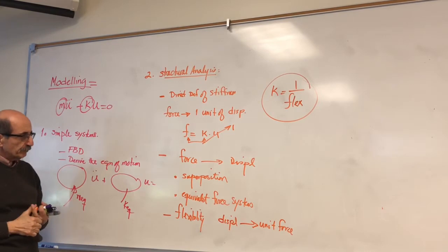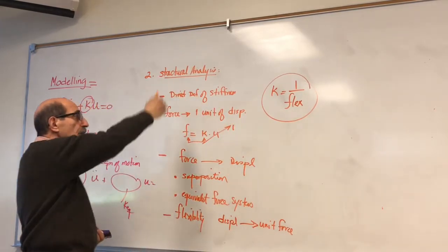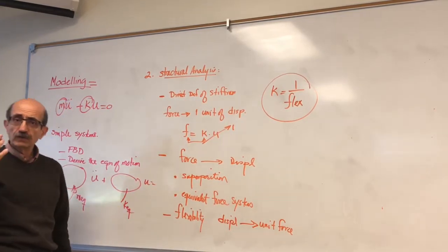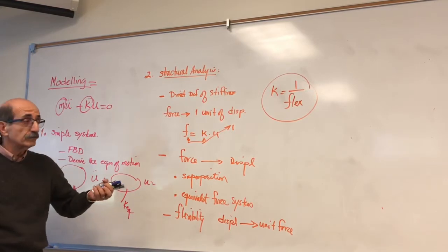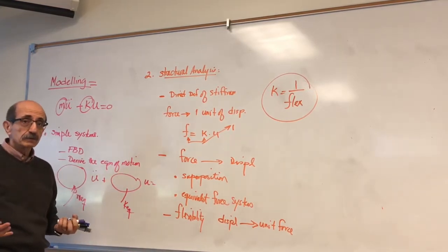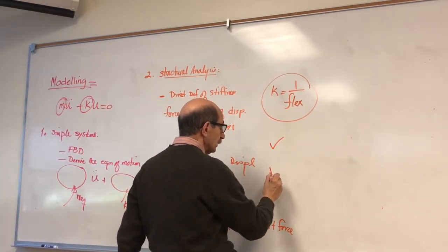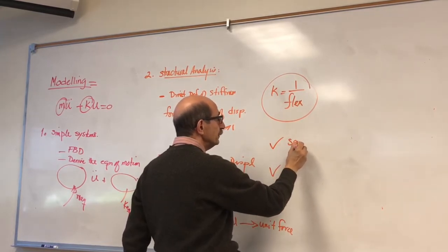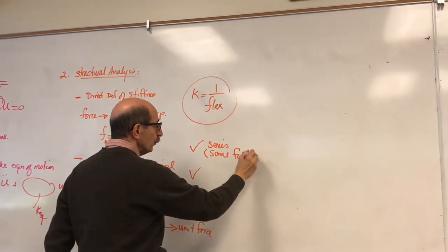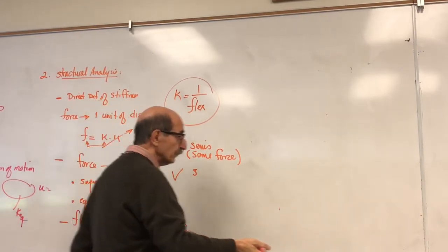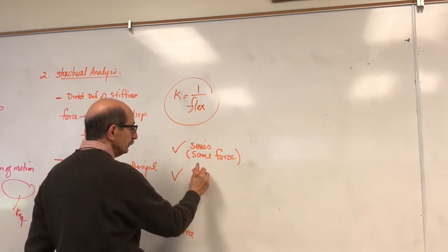So I'm going to do a few problems to cover each one of these areas and also demonstrate that in all of these, remember, two general concepts are very important, especially if you have a system made of many components: how to add up the effect of these different stiffness components, which we describe as the concept of springs in series, meaning springs or stiffnesses that are subjected to the same force, or springs in parallel, which are stiffnesses that go through the same displacement.